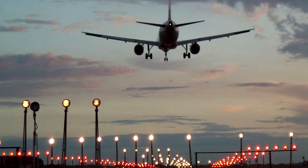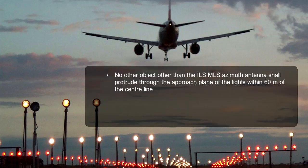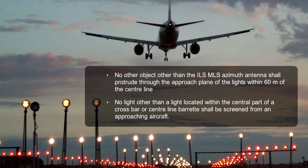In all cases, all lights shall lie as near as practicable to the horizontal plane passing through the threshold, provided that no other object other than the ILS-MLS azimuth antenna shall protrude through the approach plane of the lights within 60 meters of the centerline, and no light other than a light located within the central part of the crossbar or a centerline barrette shall be screened from the approaching aircraft.